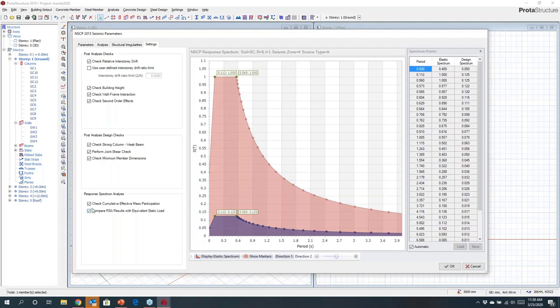Okay. We will check for mass participation. We'll also check that the minimum dimensions meet the code, so that you're not putting in elements that don't satisfy the code of practice. Other important checks that we do is for joint shear. We will check joint shear. We will make consideration for where you may have elements eccentrically framing into a column.